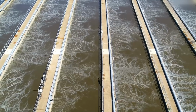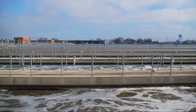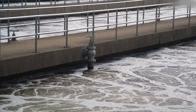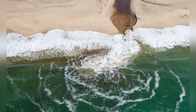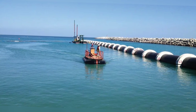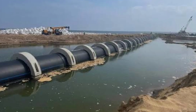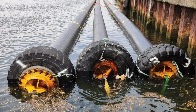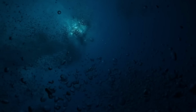For coastal plants, the most common destination for this brine is back to the ocean. But releasing a dense stream of concentrated seawater from one pipe can create an area of unusually high salinity near the seabed. That means the outfall is another engineered part of the desalination system, rather than simply a drain. Many plants use offshore pipelines ending in multi-port diffusers. Instead of releasing all the brine from a single opening, the diffuser sends it through several smaller outlets at relatively high velocity. This pulls surrounding seawater into the plume and mixes the two streams much more rapidly.